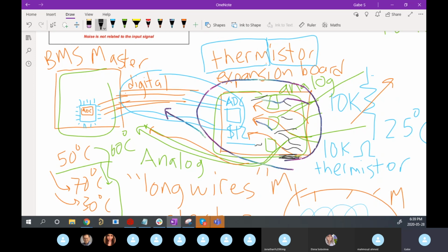And usually what happens in these wires is their return path for the ground is not traveling with them. So you may have a ground wire that goes through, but all of the analog signals that go by don't have their own ground plane coming with them the way they do on a circuit board. So sending those analog wires in free space, not on circuit boards, allows for the opportunity of them to pick up a lot of noise.